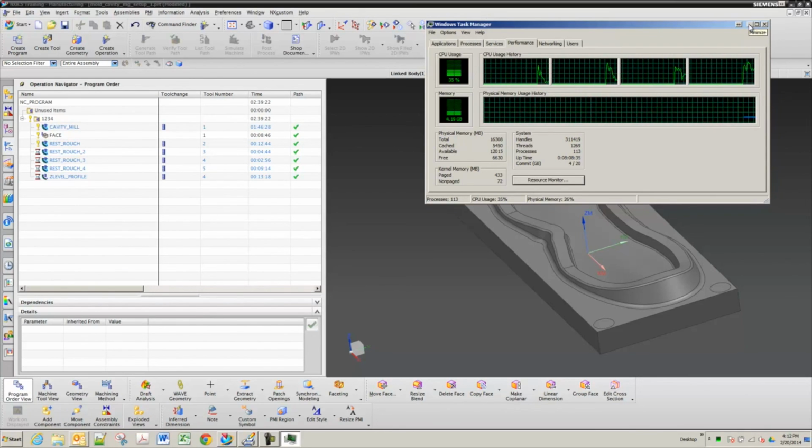And I recommend turning off hyperthreading if you're doing CAD, because all it does is take my 4 cores and split them into 8 smaller cores. It's better to have 4 more powerful cores, because a lot of times you're not using multiple cores, so the more power you can have for one is better. Bigger part.